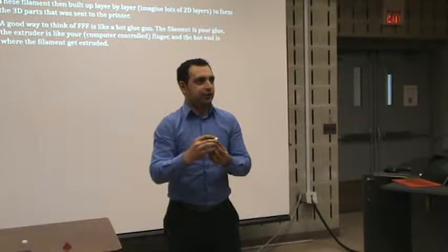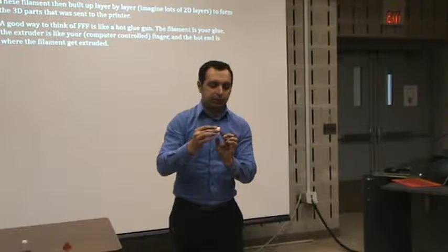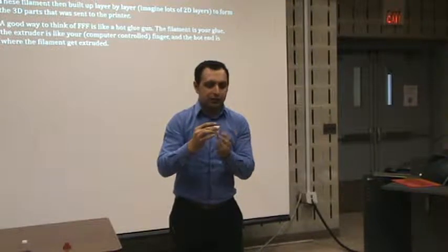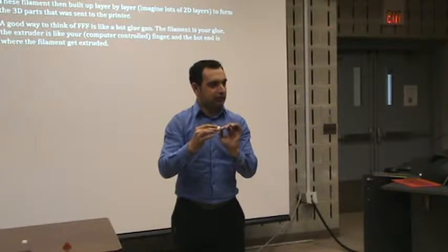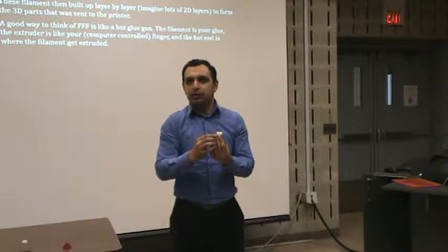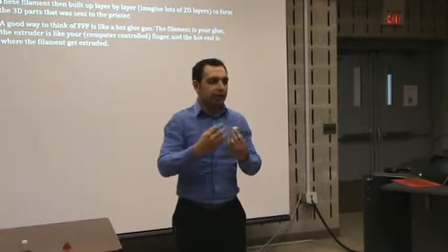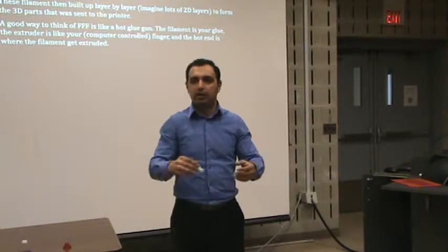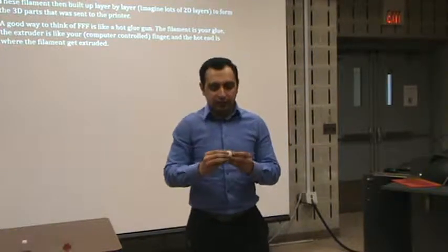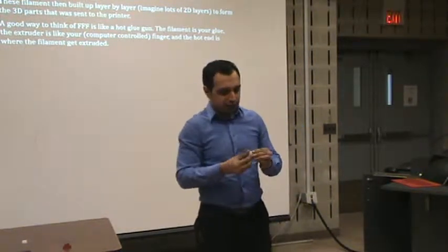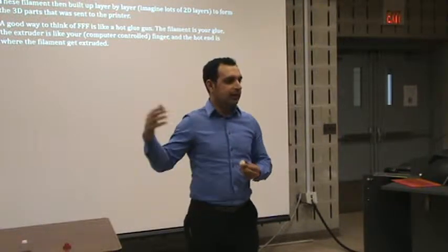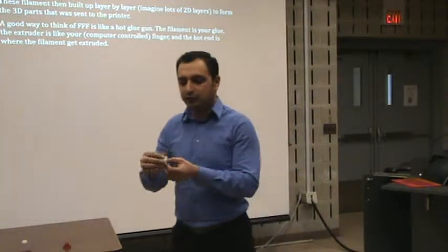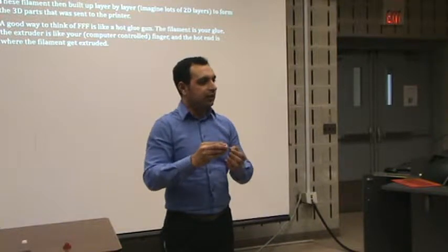And this is why you need a second extruder, because if you have a second extruder, it will build a support material, it will build small columns around it, so that when it comes to this point, the rest of the model will rest on that support, okay? And that support can either be removed, or depending upon what kind of a material it is, sometimes it is soluble, so you just dissolve it into something and all the support material will come off, and you can take the clean model out. Okay, so that is the real reason of having multiple extruders. You can have a support material loaded into one of them, and the other one will be the real build material. Or what you can do is have this as a single extruder with some kind of a thin support that you can break off.